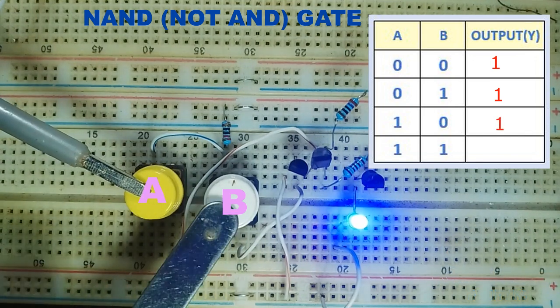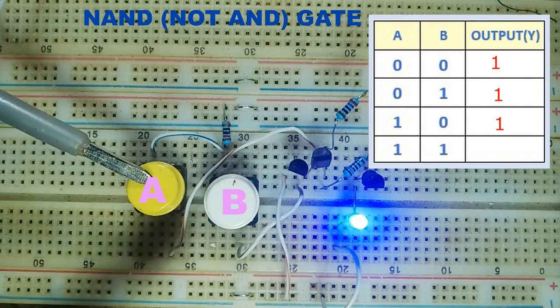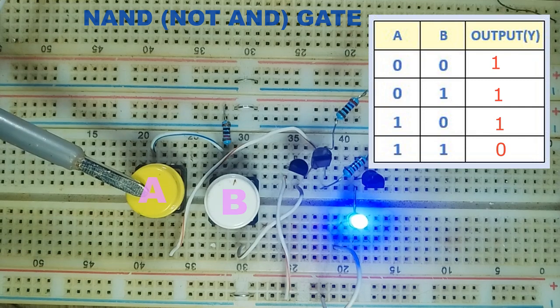Now, let's press both A and B buttons to see what happens. There you go, the LED finally goes off. When both inputs are high, the output goes low, and that verifies the truth table of a NAND gate.